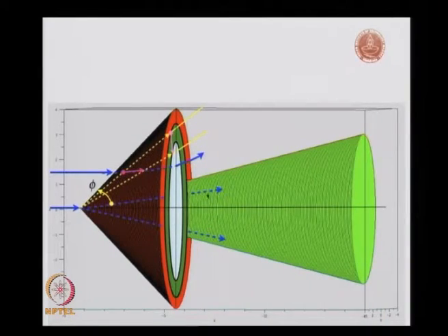So, I have a shock wave. Some of my streamlines come here and deflect, and then I encounter the shock and I encounter the solid cone. Then I just come there and move uniformly over the cone and move along its surface. So, basically these are all straight lines. So, we have straight streamlines which go on the surface of this cone.